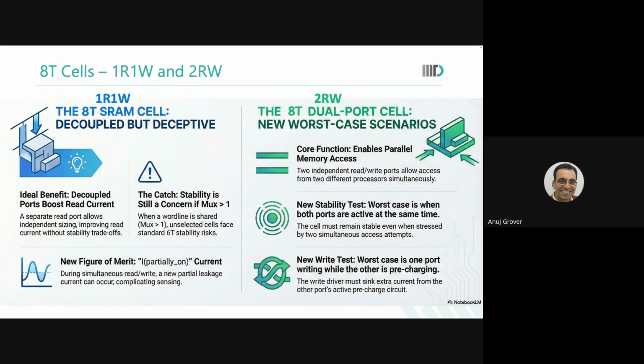And then we still had a silicon failure. And when we analyzed the failure, you know what we saw? We saw that because the two ports are asynchronous, the word line of port 1 got selected at this particular time. The word line of port 2 got selected at this particular time. So this precharge turned off here, and this precharge turned off here.